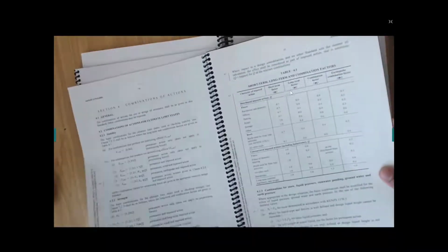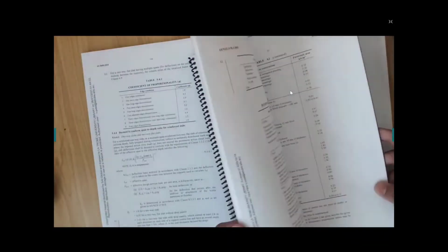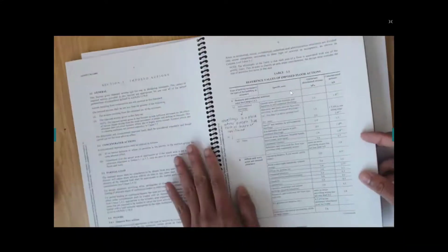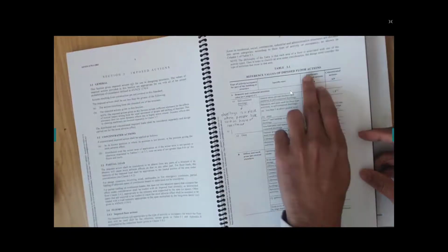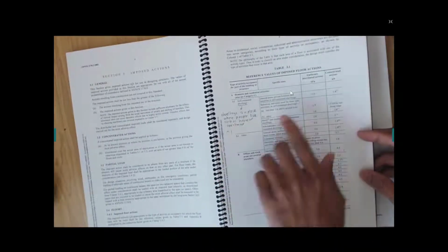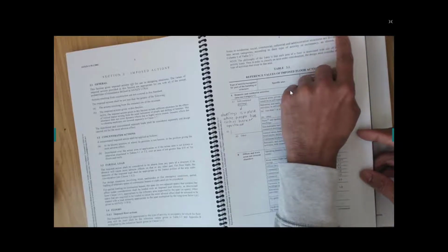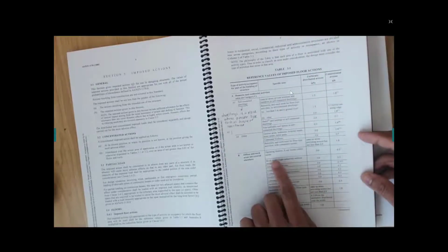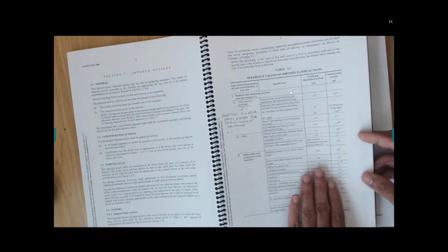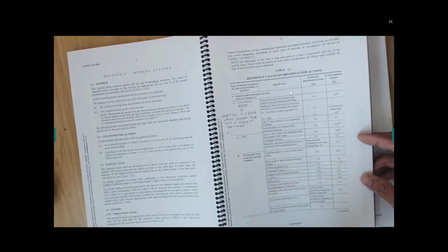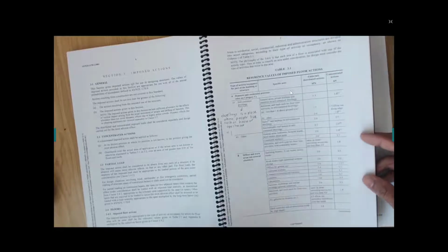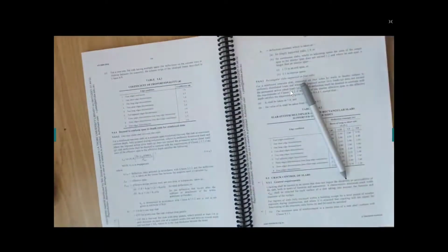But in a couple of months, when you are a graduate sitting in a design office designing some slabs, you might need to refer to this. For office buildings, we have these 3 kilopascals given, so you can again refer to AS/NZS 1170.1 in case the live load is not given. In that case you can use 3 kilopascals, typically used for general office use. So that is just a quick reference for where those values are coming from.